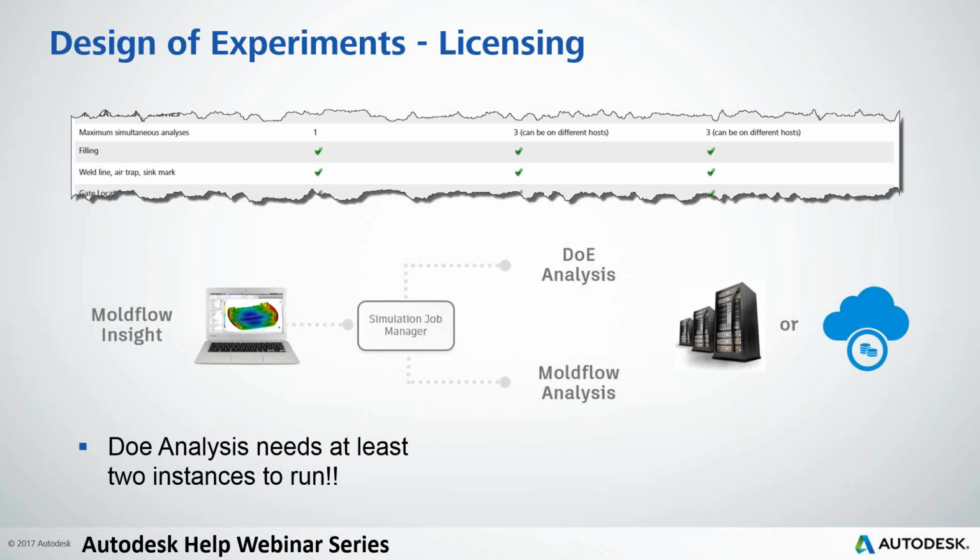This also means that the DOE could be quite a slow analysis, because if we have, let's guess, 20 runs to run in a DOE, and we have 1 license, 1 premium or 1 ultimate license, that means that we are only able to run 2 runs or 2 jobs at a time in parallel with the DOE. And this will be sequential until the 20 runs are finished.